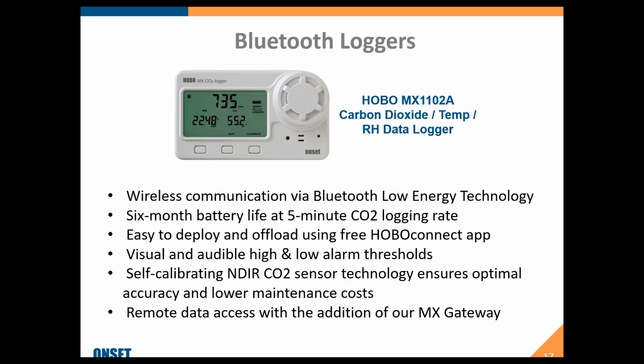Put it in its place. 8 days later, if you have that auto calibration enabled, what it will do is it'll take the lowest three consecutive readings and set that to 400. So if you're in spaces that are unoccupied, or times of unoccupied, say like a classroom, the AutoCal will be great. If it's in a spot where maybe it's occupied at all times, think a hospital, then you may want to start with just the manual calibration and then do another manual calibration 8 to 14 days later.